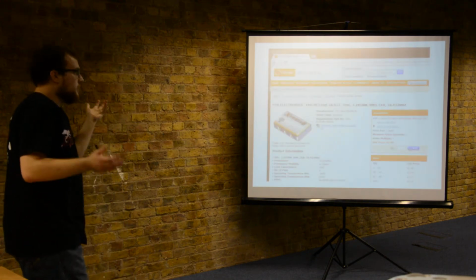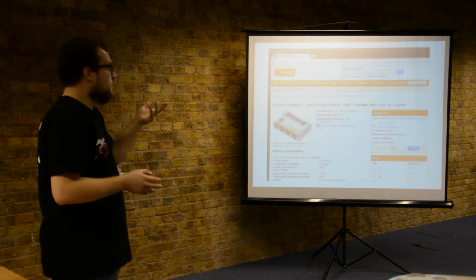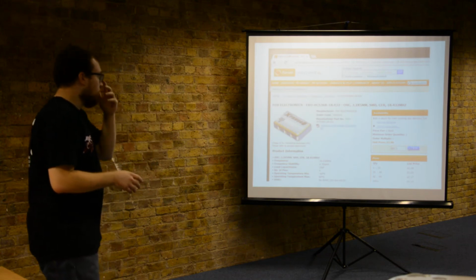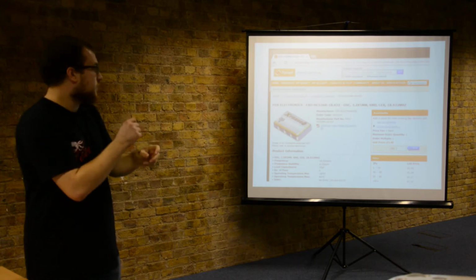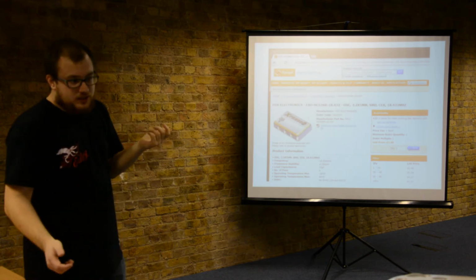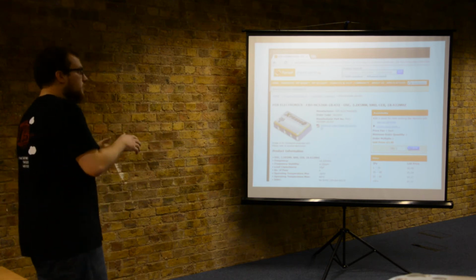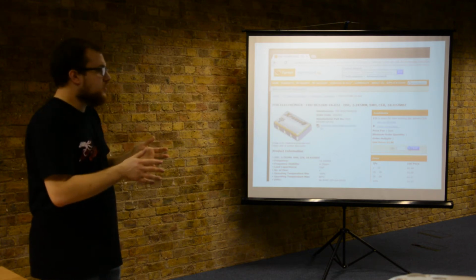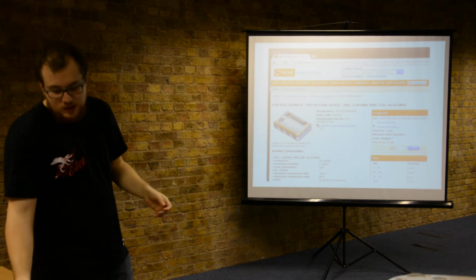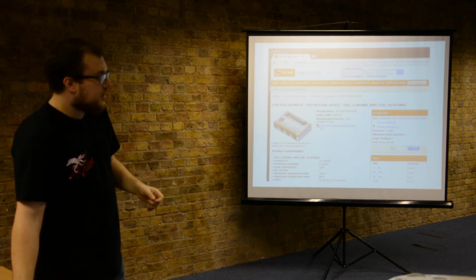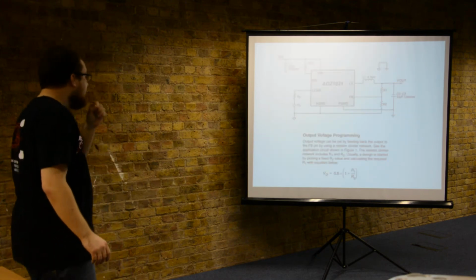Luckily, it's just a very standard 5mm by 3.2 millimeter crystal. You can just order one and desolder it and change it. But as we've discussed, after a certain frequency, you will need to increase the voltage to increase the drive strength of the signals as well. And that's where you have to dig out the data sheet for the buck regulator.